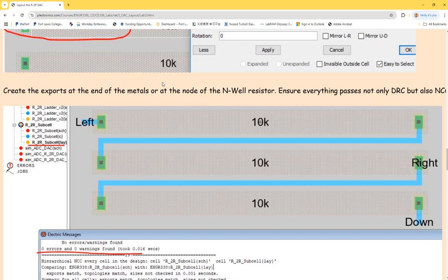Keep in mind, always, whenever you have billions of transistors, there's an error check called LVS. It's layout versus schematic. Okay? If you organize your schematic in a certain way, you want to organize your layout in that same way. It's checking your ports, checking your sub-modules, checking the values of the components, checking every single thing. So since I generated 3 resistor schematic sub-modules, I need to create 3 resistor layouts and put them into icons as well.